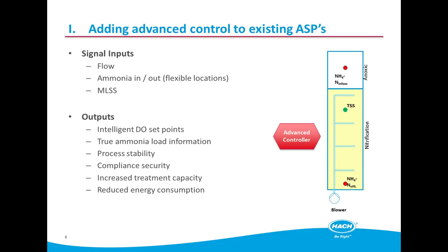So we have a controller which allows you to dial in the optimum sludge age, and that's based on the temperature of the sewage. There's a direct relationship between temperature and the correct sludge age that you can run with. A common problem is people will increase the mixed liquor to a very high level when they are receiving high loads, and sometimes the aeration capacity of the plant isn't able to match the entire biology that you've got in there.